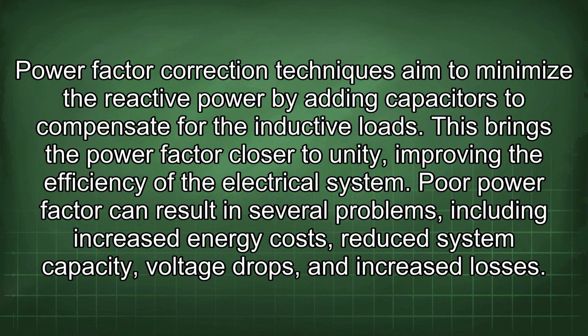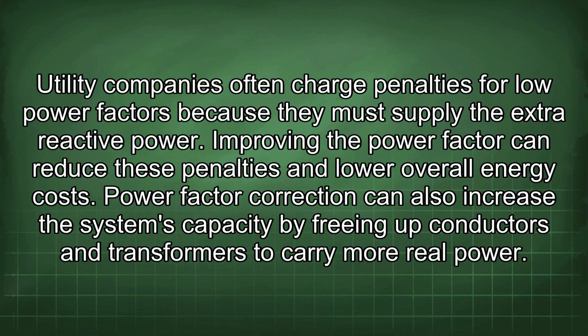Poor power factor can result in several problems, including increased energy costs, reduced system capacity, voltage drops, and increased losses. Utility companies often charge penalties for low power factors because they must supply the extra reactive power. Improving the power factor can reduce these penalties and lower overall energy costs.